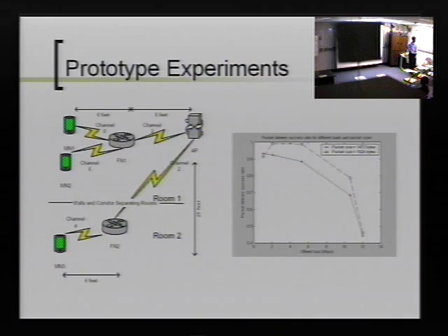So what do you do then? When you measure the distance, you adjust the transmitting energy? We look at the RSSI. There is something called an RSSI that each card reports. But do you adjust the transmitting energy? The transmit power, yeah. Yes. In fact, standard cards support only 4 or 5 levels. Oh, okay. So you play with those. Yes.